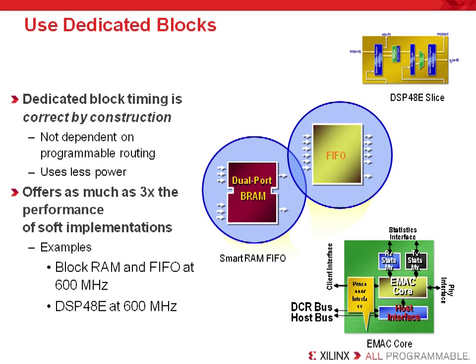So be sure to use as much of the dedicated hardware resources as your design needs, and if you think you may be running out of primary FPGA resources, consider implementing more of your design in leftover dedicated hardware resources.